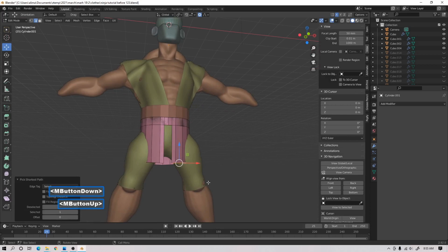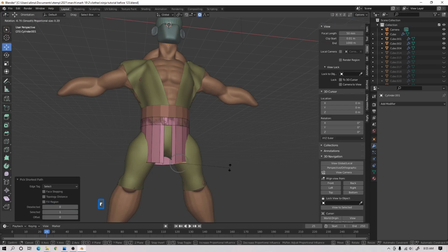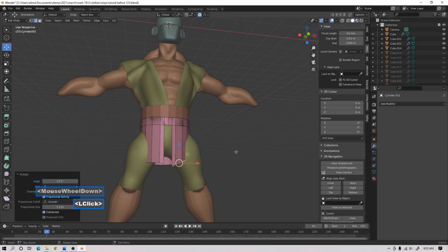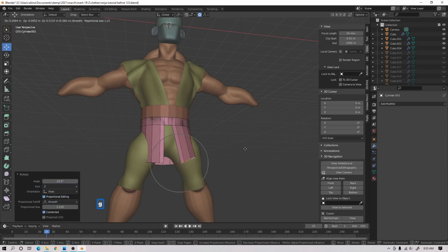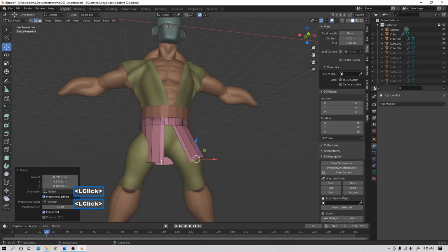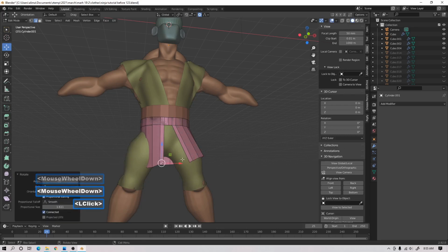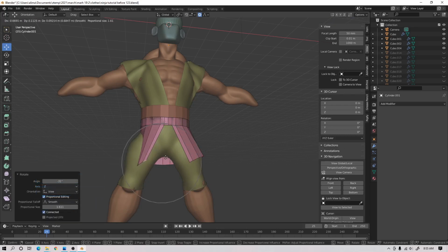We'll press R to rotate. So this is when I'm rotating, it is rotating here as well. We want to turn this off, this X. Press R to rotate, rolling this up. Now I'm going to press G to move this out to the side here. I'm going to press R to rotate. Press G.